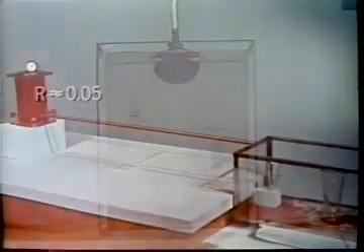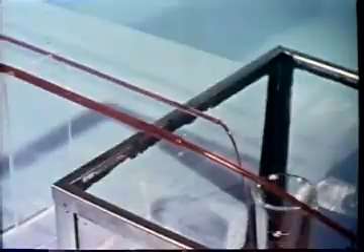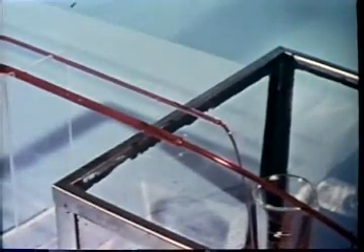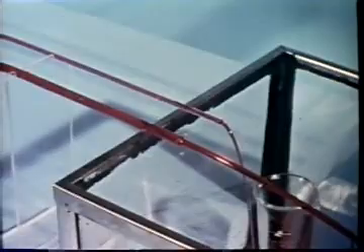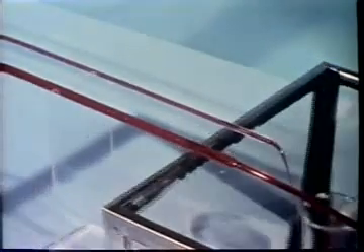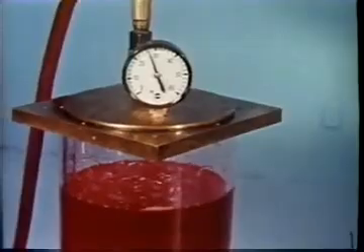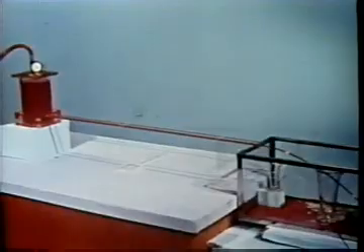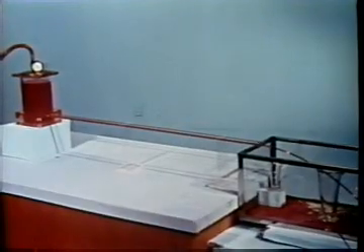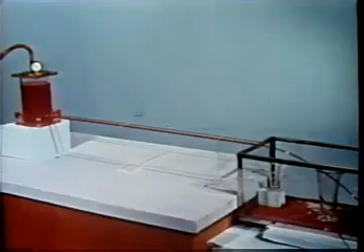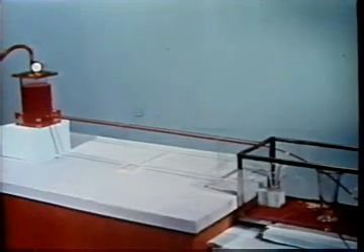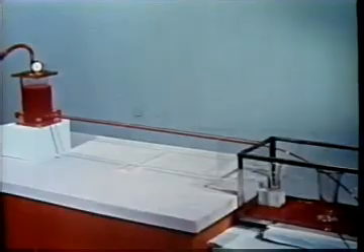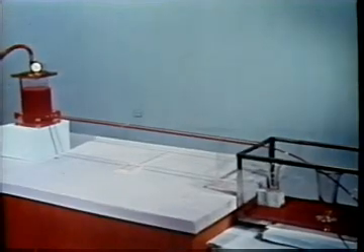However, the flow of fluid through tubes of uniform bore provides a simple case in which inertia plays no part in the mechanics of the flow. Here the tangential stress due to viscosity is balanced only by the driving pressure. Though the Reynolds number is not necessarily small, there is no change in the inertia of the flow as it passes through the tube, so that the results of calculations of the kind used in thinking about low Reynolds number flow are applicable.